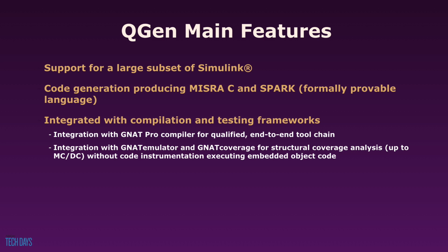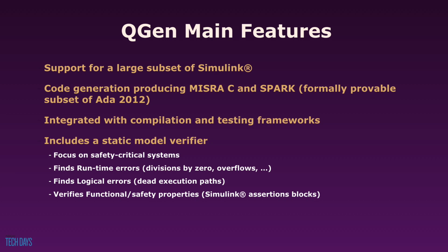You can also do coverage analysis up to the MCDC level, so that if you have a model that you've done model coverage on, you can now execute those same model tests and do object code coverage. And as I mentioned, it includes CodePeer, which is essentially a static model verifier in this sense. The point here is that a lot of these systems are safety critical, and it will find the runtime error possibilities. It will also find things like dead code and so on.